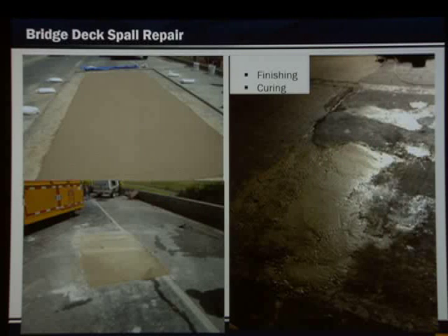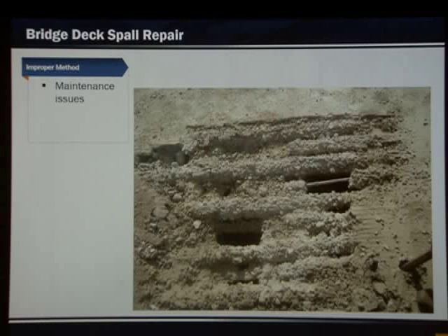You can see that some repairs turn out better than others, and that's because moist curing is often neglected due to time constraints, and that can be problematic in the future. You want to cure as long as possible. Even a couple of hours can make a big difference, but 72 hours is the ideal. And this is what you don't want. Here's an example of an improper deck repair. This manual is going to help you select the method and the materials that are going to give you the best results and give you confidence that you're going to have long-term results, and you want to avoid future maintenance issues.